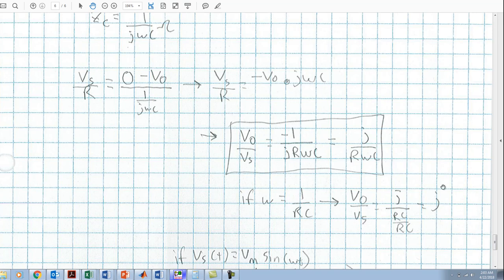Now, if we go ahead and plug in what we were asked, if omega is equal to 1 over RC, then V naught over Vs is just going to be j over RC. And so in that case, what you're just going to have is j.